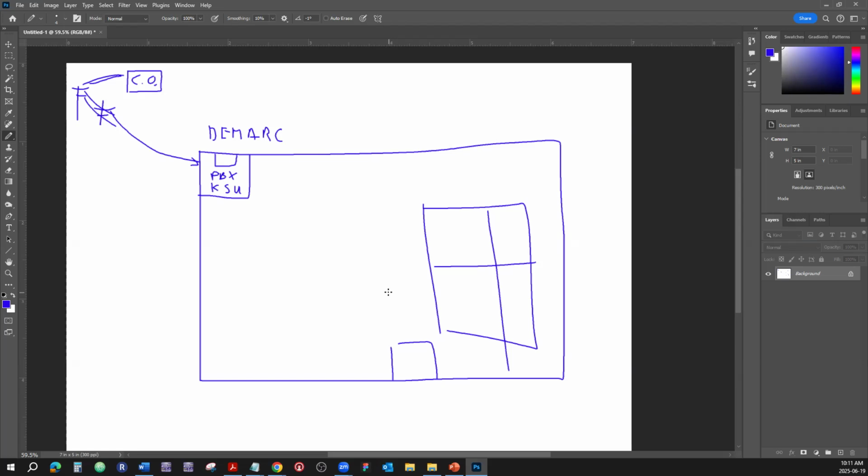That's why we have those telephone systems that are called 616 or 3x8. So 616, 6x16, means 6 CO lines and 16 extensions. That's a pretty good balance between available lines to make a connection outside and 16 telephones. It works pretty okay, usually. Or 3x8 and so on. Or you can get modular systems where you just add the lines as you need.